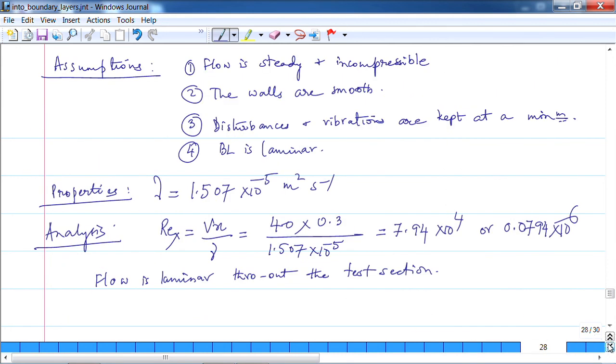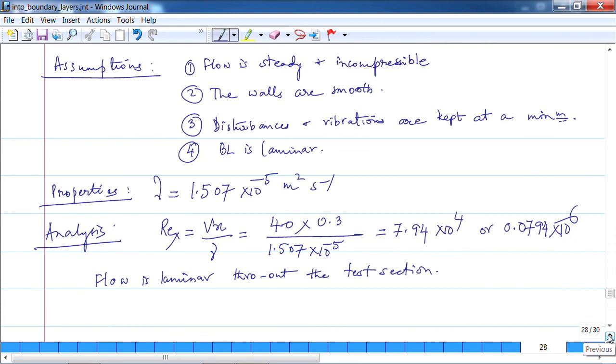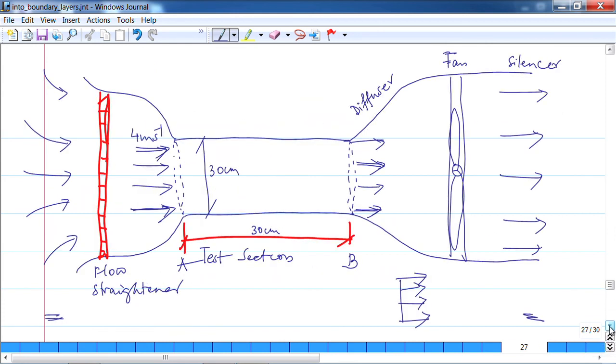What we have here is a diffuser, and then the wall straightens out. But because of the boundary layer, the displacement thickness is almost acting like a thickness of the wall.